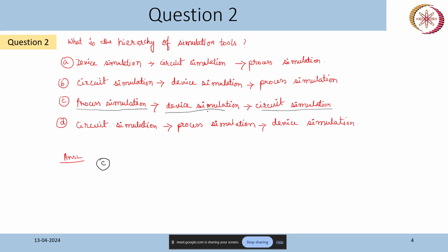So the doping concentration should be much less than that. We cannot get doping concentration close to 10 to the power 22 or more. So we have to first know what limitations we have in our processes, and then go for device simulation. Based on the devices we can achieve, we design our circuit or system. Okay.